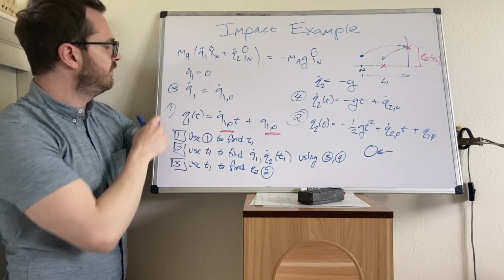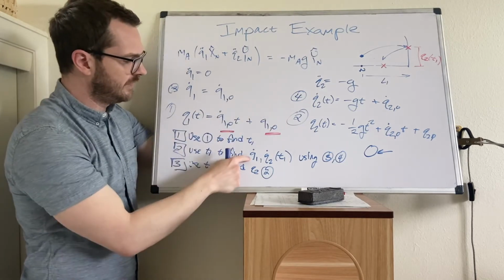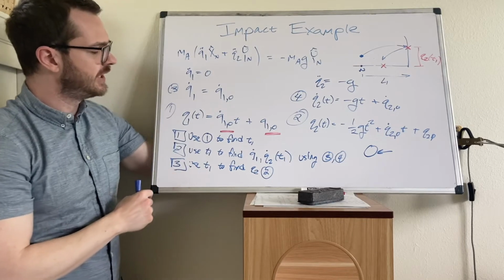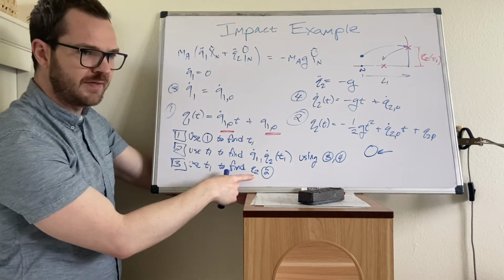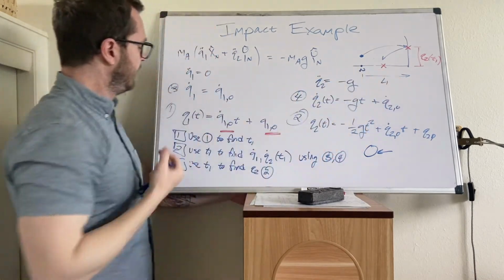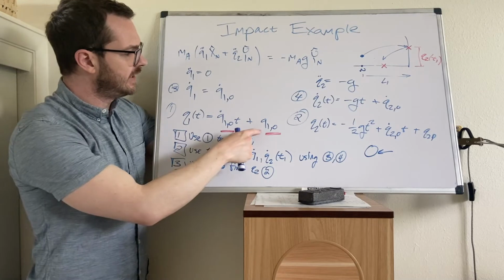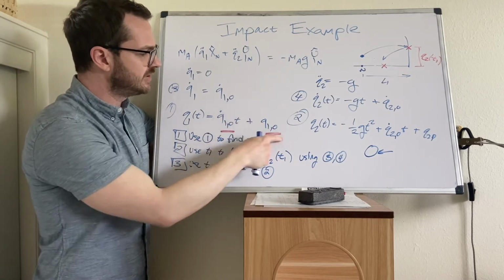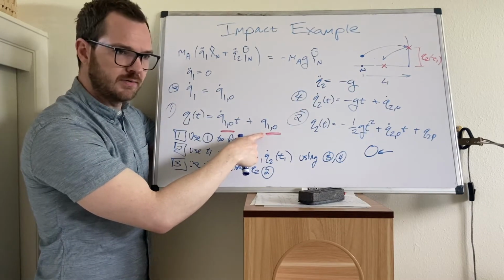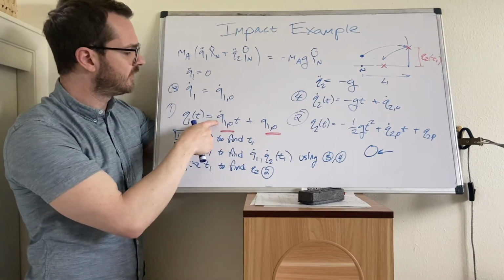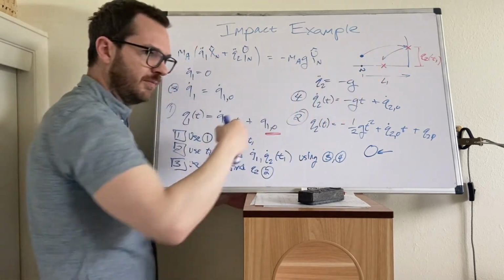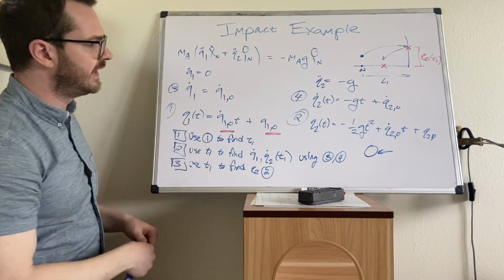We can use the time in equations 3 and 4 to get the new speeds. And this time, the number 3 is going to change. And instead of finding Q2 at this new impact, now we'll be looking for the x coordinates. And that's simply equation number 1. So again, what's the initial condition for the second ballistic phase? It's at the wall. So this would be L1, right? Whatever the value of L1 is. And then this Q1 dot we have solved for, this new speed, is the speed coming out of that first impact. Okay, so the process is effectively the same.